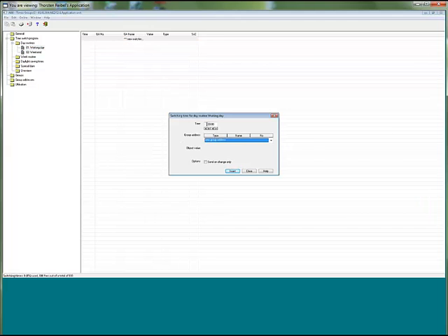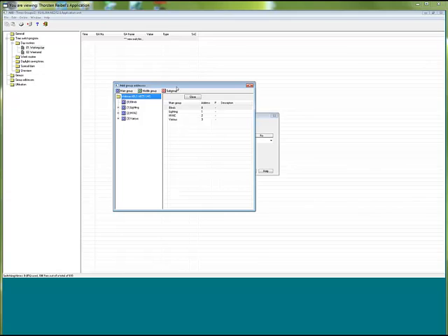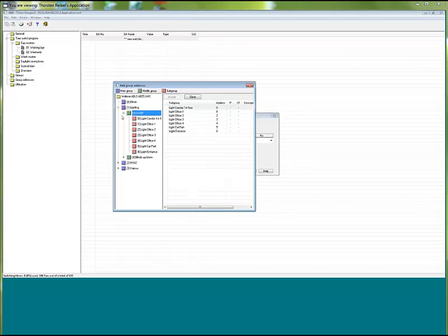Very simple. You adjust the time here. Maybe 10 o'clock in the evening. And then, of course, you would like to say which group address shall be sent out at 10 o'clock in the evening. You have to select a group address. And if you click here, new group address, a window will appear showing you all the group addresses you have used already in the ETS. For example, for lighting on off, I have here group address light 1, light office 1. You have to click here on the middle group, then you select here the group address and accept this.